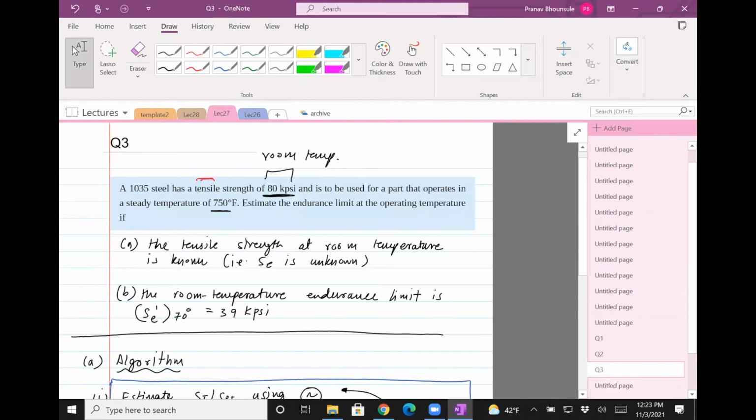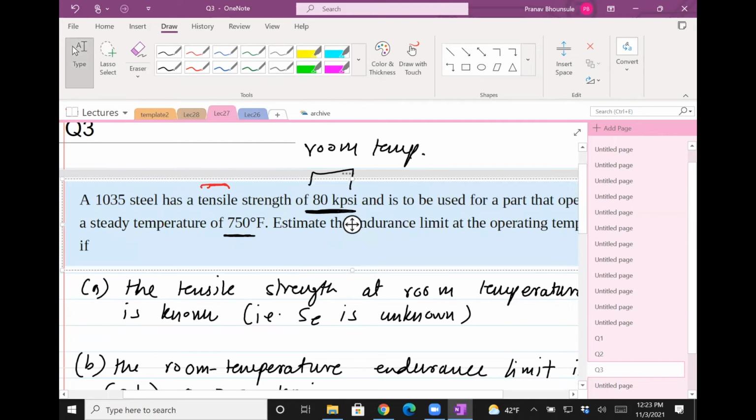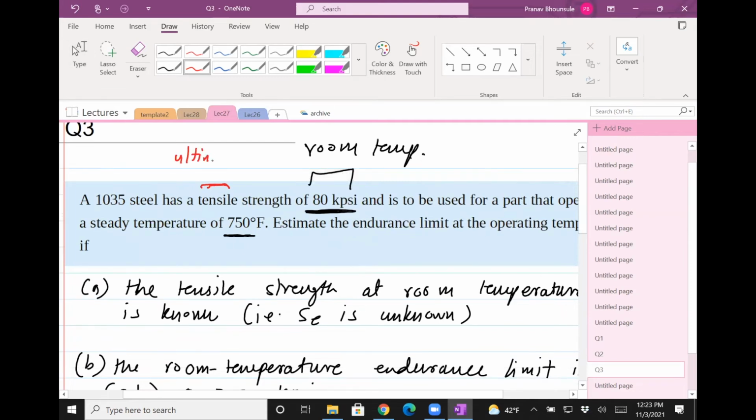When they say tensile strength, it just means tensile strength to failure. So it's the ultimate tensile strength. In the absence of the word ultimate, we assume that's the ultimate strength. That's where the stress strain curve takes that inflection. It just reaches the maximum.